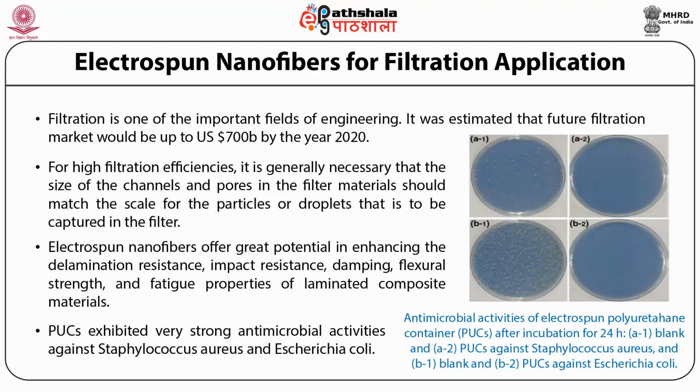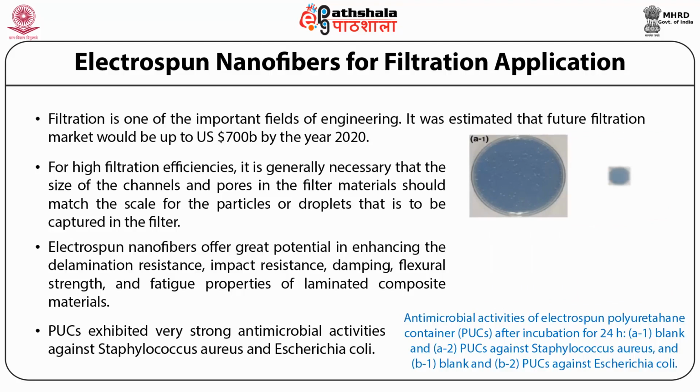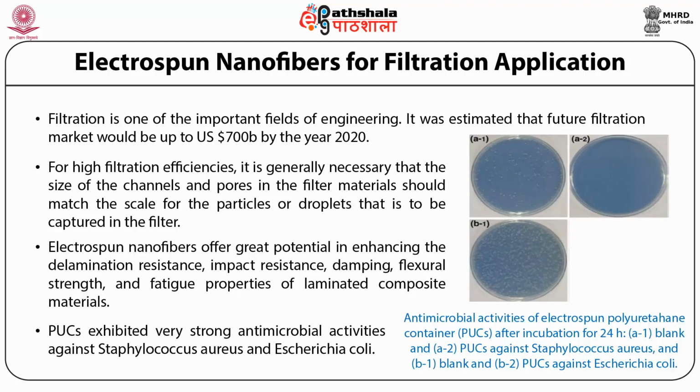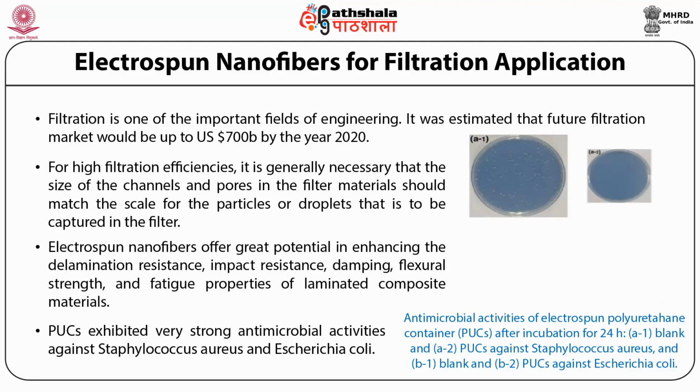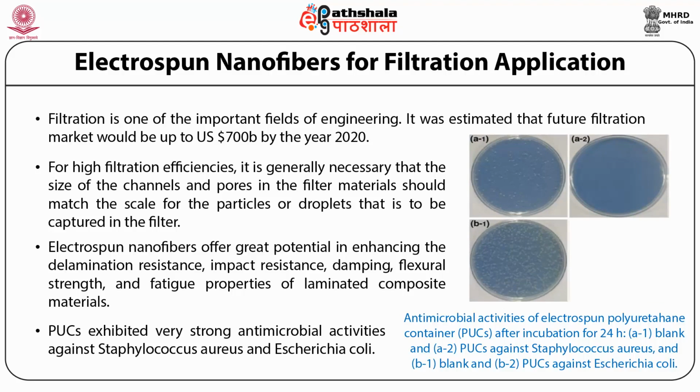As the diameter of the polystyrene particle is greater than or equal to 1 µm, the removal efficiency can be 100%. When the diameter of polystyrene is 0.5 µm, the removal efficiency is higher than 90%.